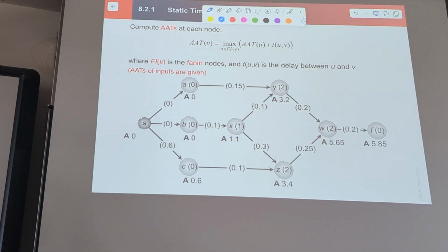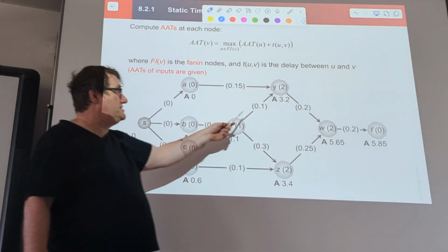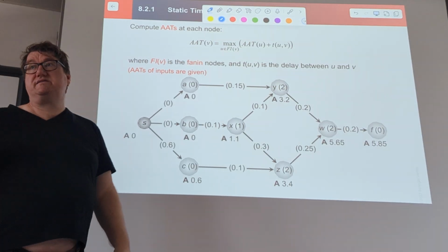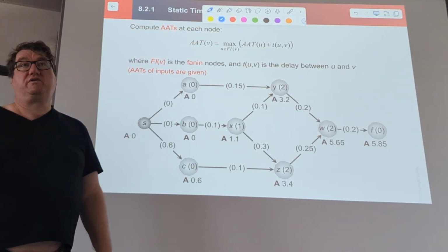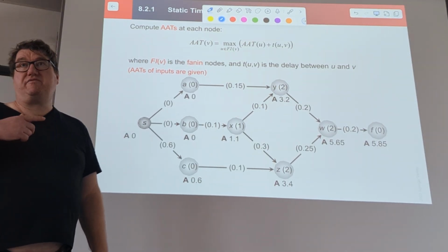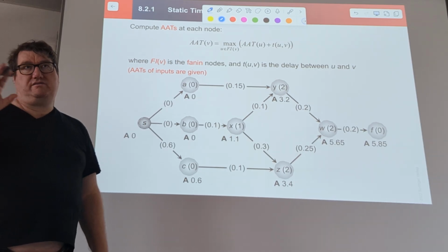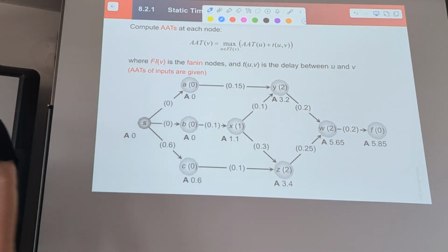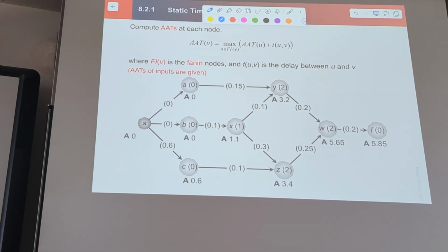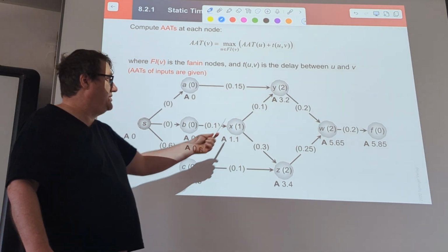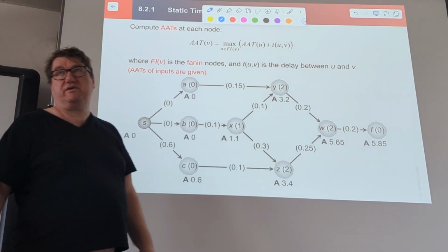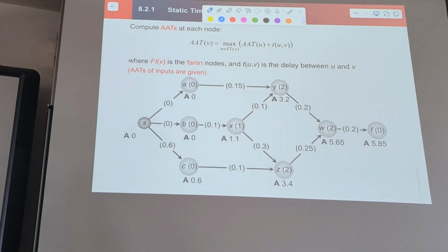So we basically reduce it to the signal that arrives latest at our gate. Here we still have not modeled, as in the Liberty file, that every input has a different timing arc to the output, but you could add that. Here it's just the wire delay. So we end up latest at 3.2 nanoseconds at the output of that gate.